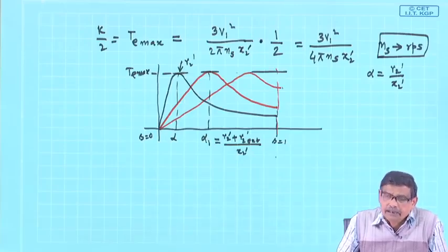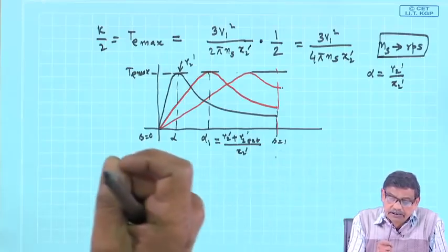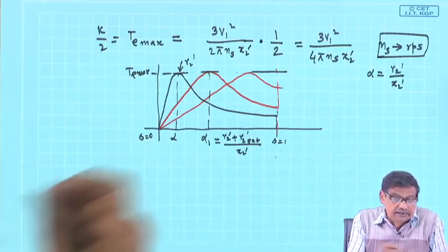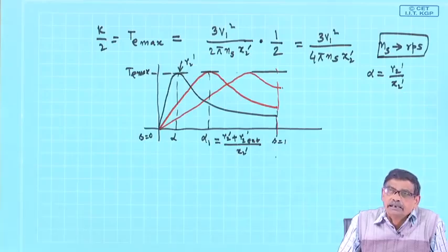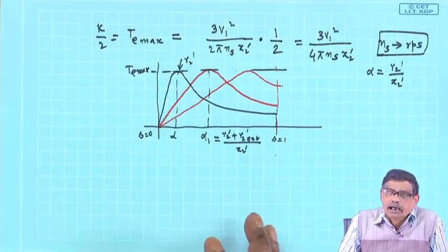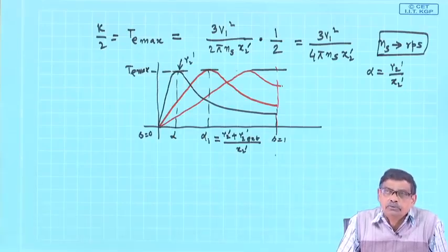So, I will calculate the value of the slip and substitute that value of the slip in the appropriate formula to get the torque, how much mechanical power it produces, the amount of torque into 2 pi nr, all these things I can do at any value of slip you want me to do that.